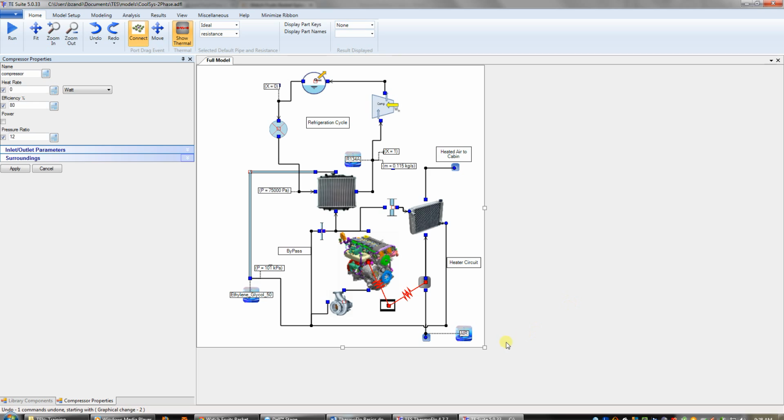In the standard or flow network mode, various subsystems are represented by flow bars in a ThermoFlo model. Flow bars are virtual flow devices with a single inlet and a single outlet. Various flow bars are connected to each other using endpoints. Endpoints are ideal connectors with zero volume and zero flow losses. Therefore, the possible associated losses must be taken into account by the connecting flow bars.